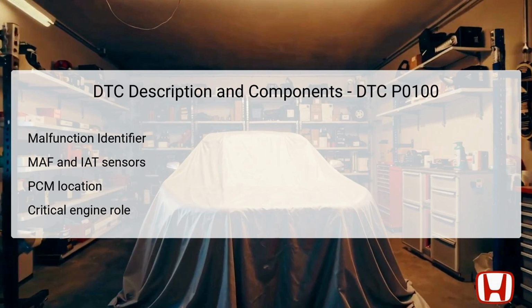The PCM is usually located in the engine compartment near the firewall and is responsible for processing data from multiple sensors to optimize fuel mixture and ignition timing. When this DTC is set, it indicates that there is a disruption in the MAF sensor circuit, which could adversely affect engine operational efficiency and performance.